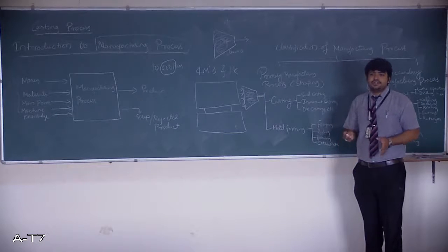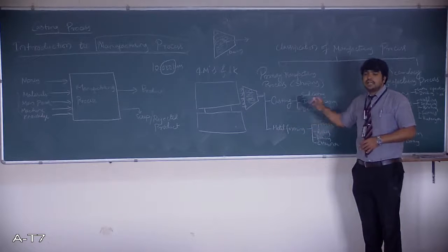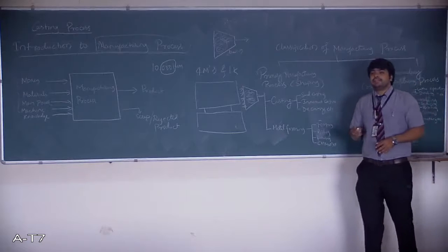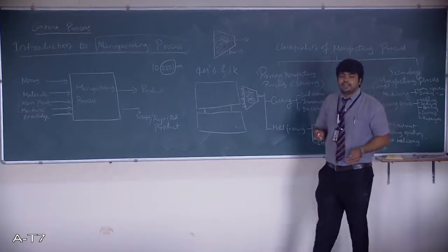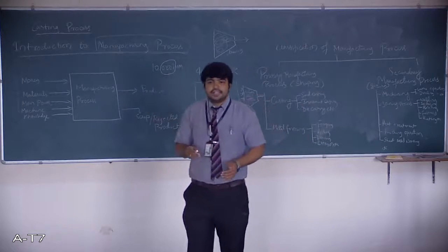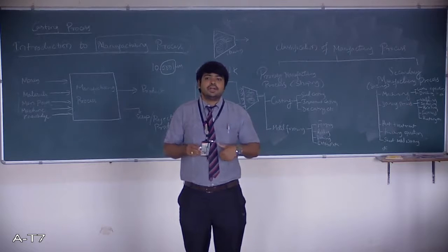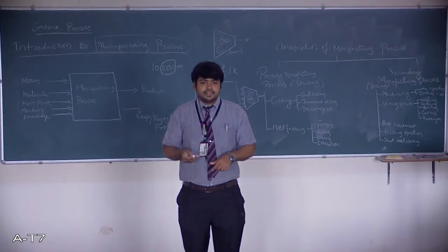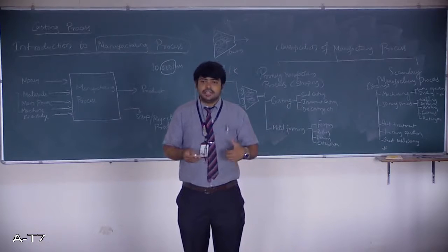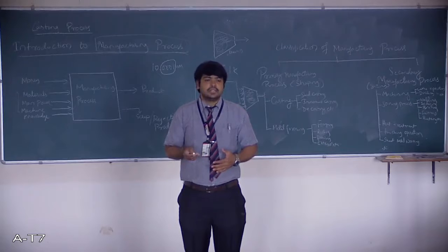So what we do is we take a standard component that is manufactured by either of these two processes, and then those are machined. For example, in the market you get a 20 mm bar, but for your engineering application you are going to use a 19 mm bar. So at that time we are going to reduce the diameter. For that we make use of lathe operation. In lathe operation we call this operation of reducing the diameter as turning.